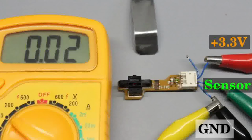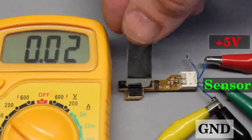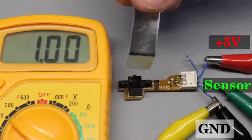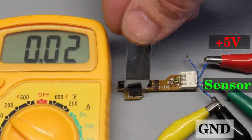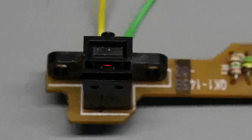If you don't get clear signals close to 3.3V when blocked and close to 0V with the metal sheet removed, try 5V. If you need 5V in your application at all costs, you can try 5V even after a successful test at 3.3V. Be warned that a too high voltage will destroy your sensor unit immediately. Well, this sensor passed the second test run. You can see the LED shining red at this type of sensor.